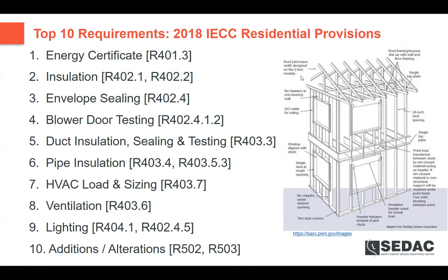As far as the insulation, someone did point out that if you're going to insulate only 4 foot down rather than the 10 foot that the code calls out, you do need the higher level of insulation of the 15 or 19. So that's very important to observe, to make sure that you're using the right amount. That's where you have to use a higher amount if you're going only 4 foot down versus the full 10.